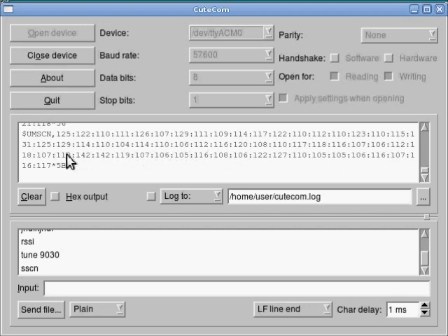Signals coming in in the 130 range are pretty far away, so we should be able to pick up anything above 130, 140 around here, and on some of these channels we're way down around 104, 110, which means that we're going to have pretty good receive range on this particular installation at this particular location. So I wouldn't say that noise is going to be a problem here at all.